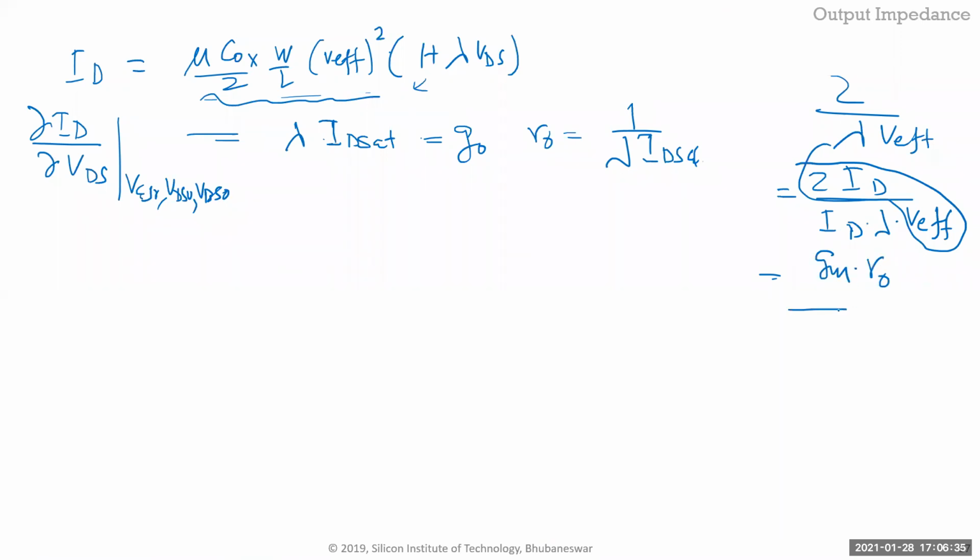R naught. So when we do the small signal modeling, maybe I'll give this to you as an exercise. Once I finish the small signal model, you can go back to that same problem, substitute the small signals, calculate the Vout over VID, and you should get the same quantity. That way at least it'll tell you that you don't mess up anything. So that's your output impedance, and then the substrate conductance is next.